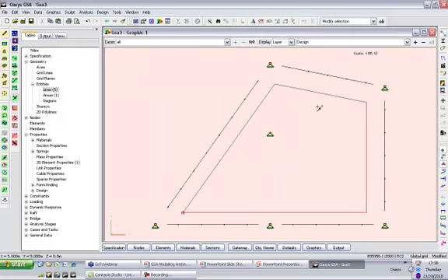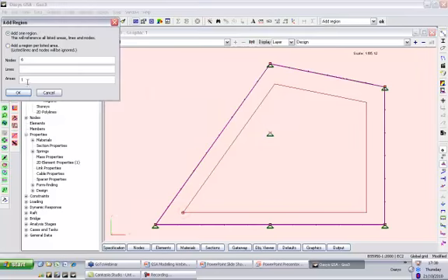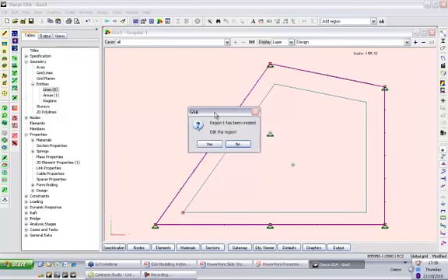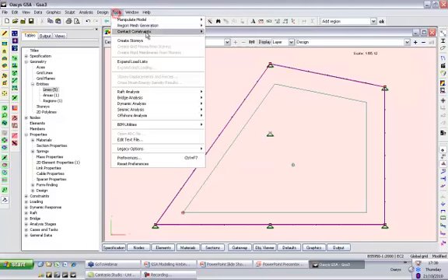Now if I select this node there and select that area and right click and add a region, yes, it picks up that area, picks up that node. We don't need the other nodes, there are other lines there, all included automatically. Let's not edit the mode, I shall come back to that, and we can now generate that mesh.